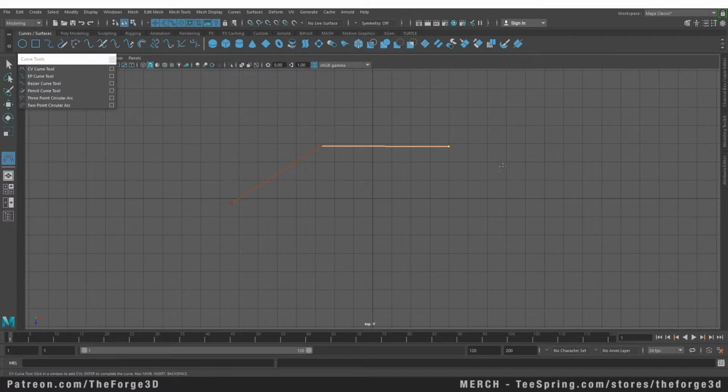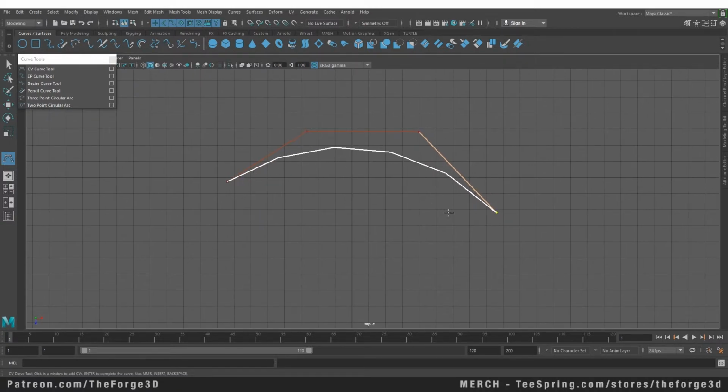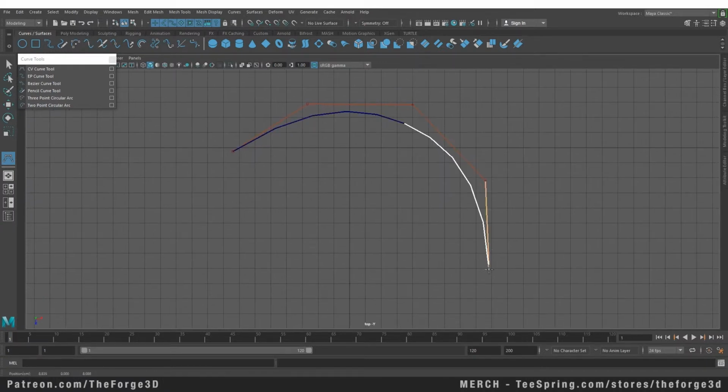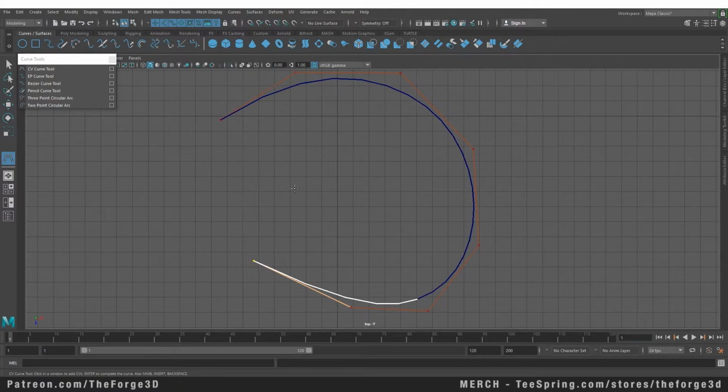And as soon as we click on the grid for the fourth time, you're gonna see it's gonna give us a curve. Now this kind of works the same way as your subdivision works. It's gonna calculate the cage and give you a curve with the average curvature. And every click that you make after that, it's gonna continue making that curve. And you can finalize this curve by pressing the enter key on your keyboard or going to your move tool.